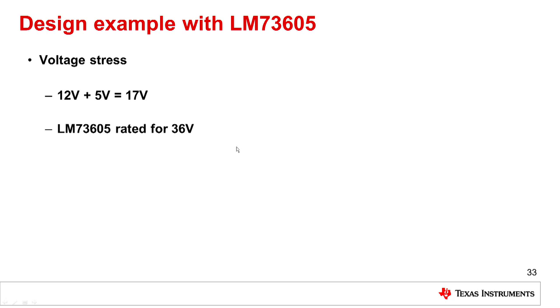Let's take a look at the voltage stress. Well, 12 volts plus 5 volts is only 17 volts, and since this device is rated for 36 volts, there's no problem there.